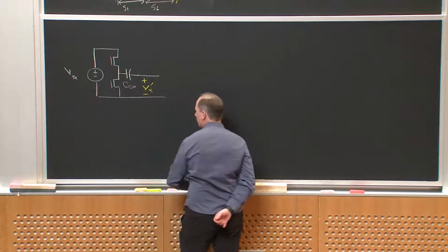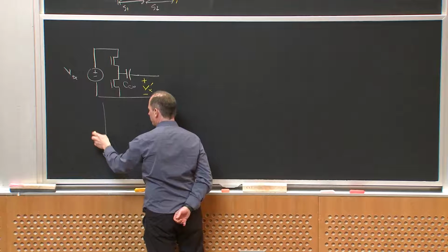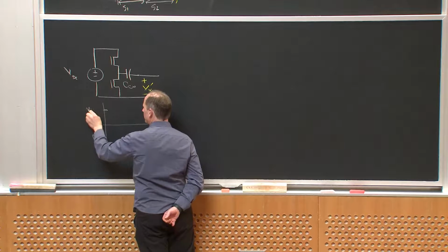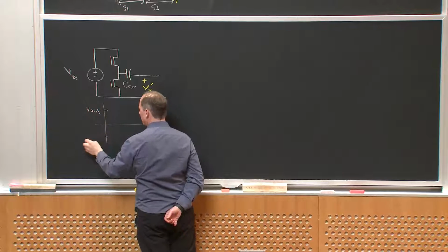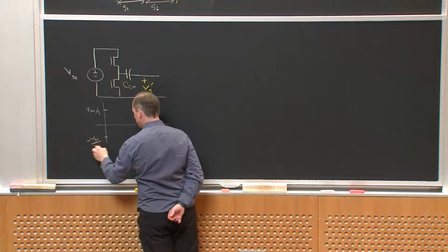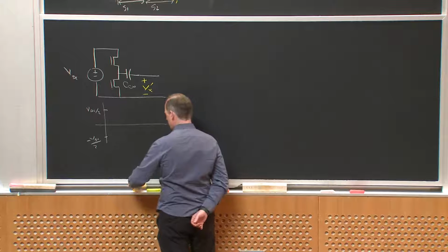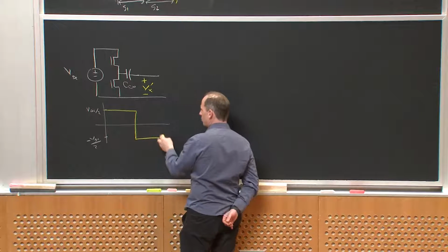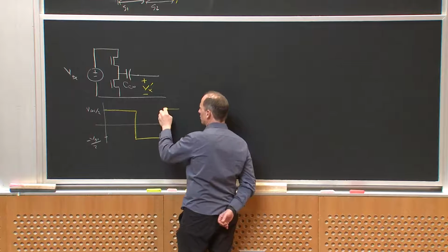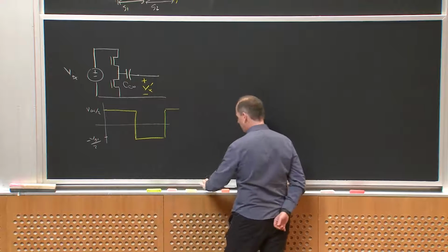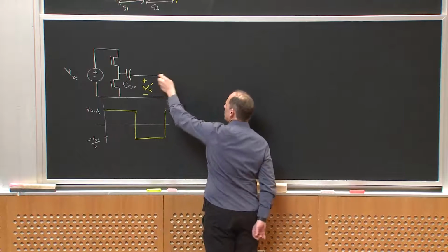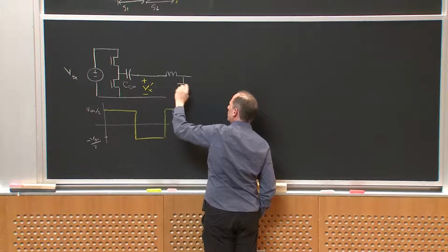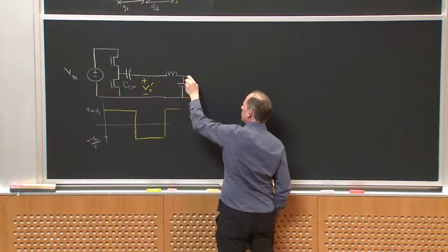Vx prime is again just going to be a square wave, going between VDC over 2 and minus VDC over 2. I'm putting a blocking capacitor in there just to extract out the AC component, which I'm using to drive the network. And then here's my parallel resonant network.